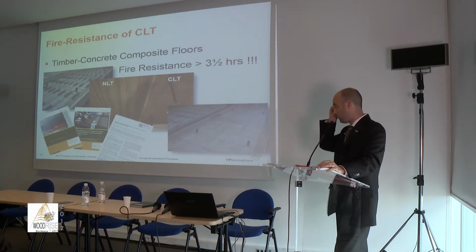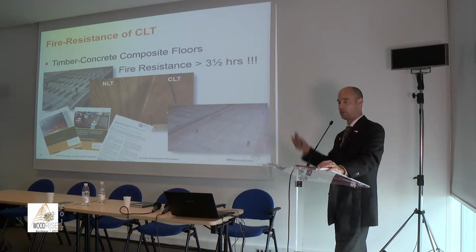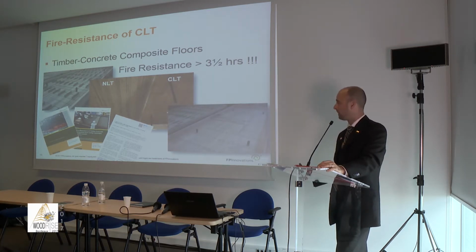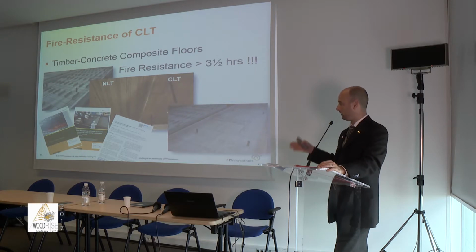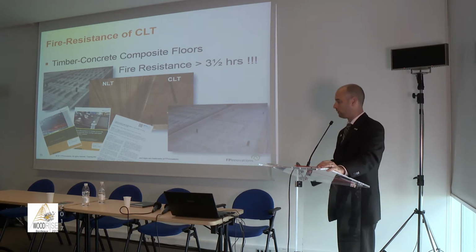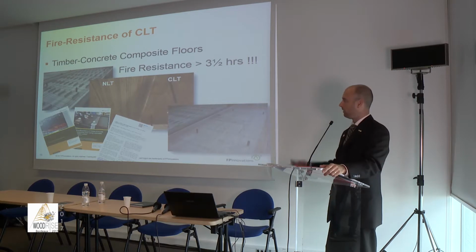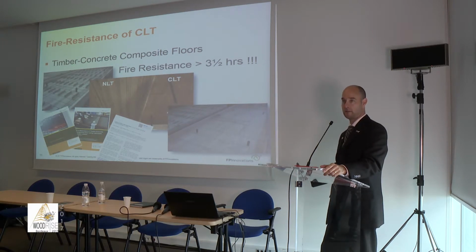We also tested timber-concrete composite. There was some talk this morning on the main stage that there's a need also for longer spans, composite with timber, for improving vibration and acoustics. So we tested 3 assemblies, and they easily reached beyond 3.5 hours of fire resistance.